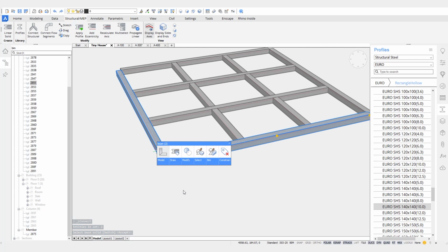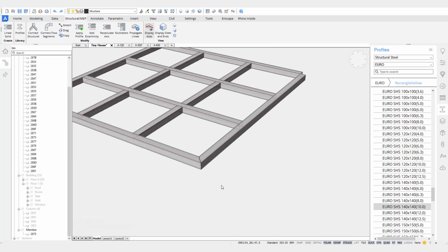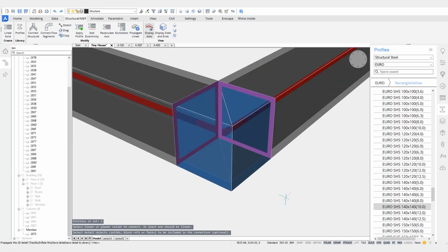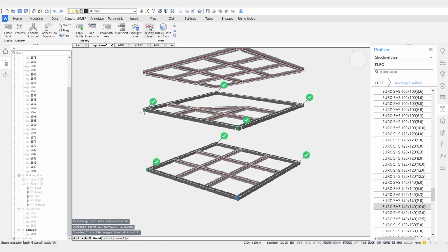I want to have a mitered, but actually I can go here again and miter these again manually, but a user that knows BricsCAD BIM will also know that there's a tool for this. It's called Propagate. So we can very easily propagate this detail all around our building. In this case, it should find 12 possible locations where it can find these miters.